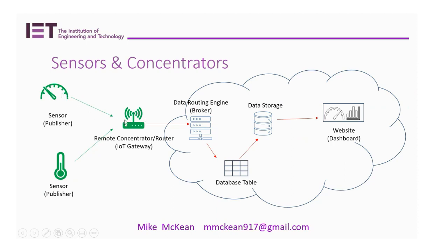And let me tell you why that's important. If you've got several hundred devices here in the smart homes world, then one thing you need to be really careful of is that's a shared bus. If you get any noise on one sensor, you share that noise with the others. If you've got 250 devices and you've got noise coming from one device, that noise is shared across all the devices. So one of the things you might have is something called ground loop or earth loop.